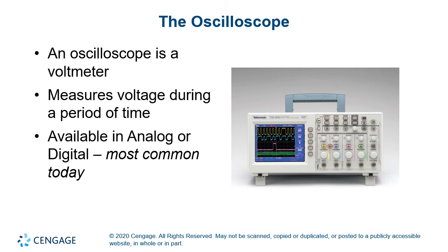Now, the last of the devices we're going to look at in this unit is the oscilloscope. Right? It's a little more complicated device for certain. Take a look over here. It has a screen with a readout. It could be an analog readout or it could be a digital readout. Most of the ones you're going to see are digital. A large number of switches over here to control various settings. We'll talk a little bit about those. And then, of course, a number of ports for connecting up your various probes, right? Essentially conductors that allow you to attach out to different parts of the circuit.